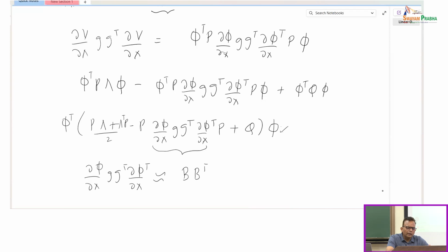There is further refinement to this, because here you're working with this principal eigenfunction, where the principal eigenfunctions are limited to a certain region. Hence, the optimal control that you end up designing, or the optimal value function that you ended up computing, is also restricted to a certain region, right? But we know that if I solve the HJB equation globally, I could get a global optimal control. So how do I get a global value function which is not restricted to a particular region? The way you do that is a little more involved, and I'm skipping that. I'm not going to talk about that in any further detail.